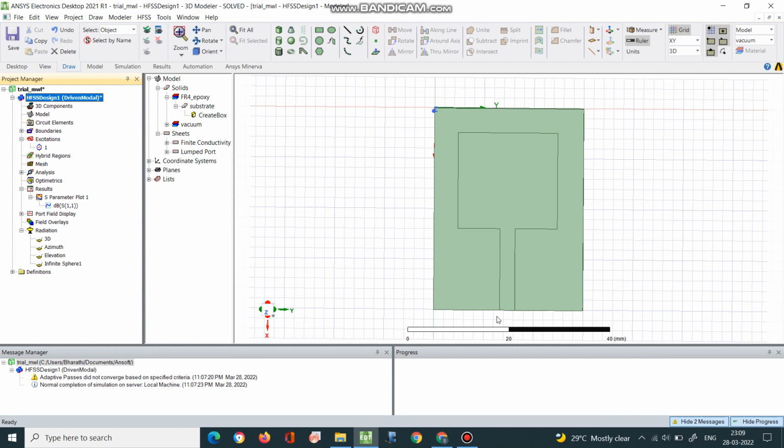We are ensuring whether all the electromagnetic waves connected at the port are transmitted to the specified structure. If you have any impedance mismatch, it will be reflected back. If your impedance is perfectly matched, that is, the characteristic impedance of your structure is perfectly matched to the characteristic impedance of the port, then you will not have any reflections. So if there are no reflections, the reflection coefficient will be nearer to 0, right?